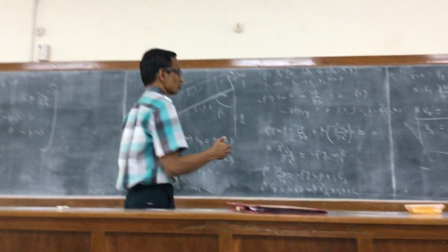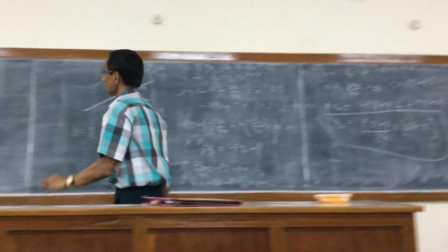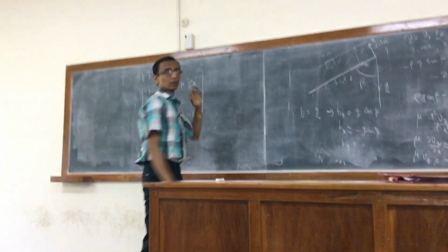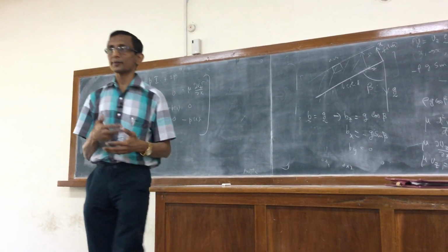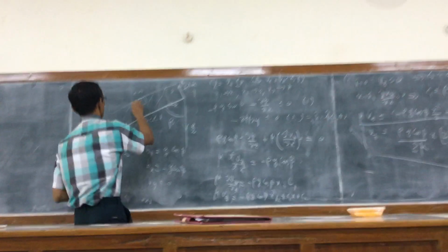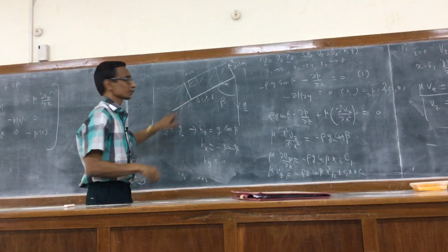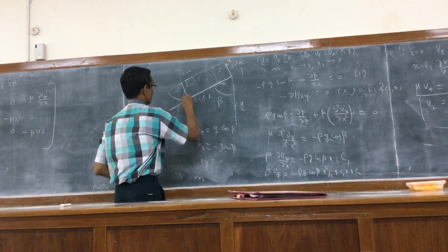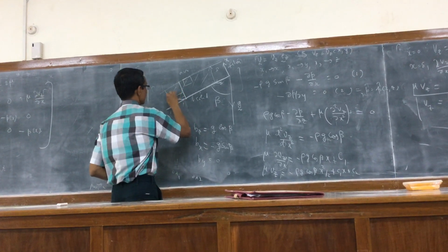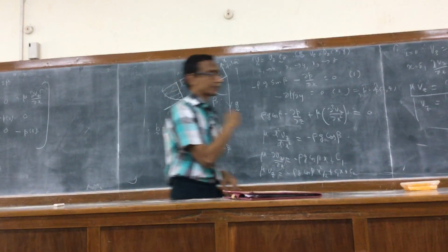Now we can use this information because we know the stress. We can look at the kind of forces experienced by the fluid. The velocity profile itself will be parabolic. It will be 0 here, so it can be plotted in this manner, and we reach a maximum at x equal to delta.